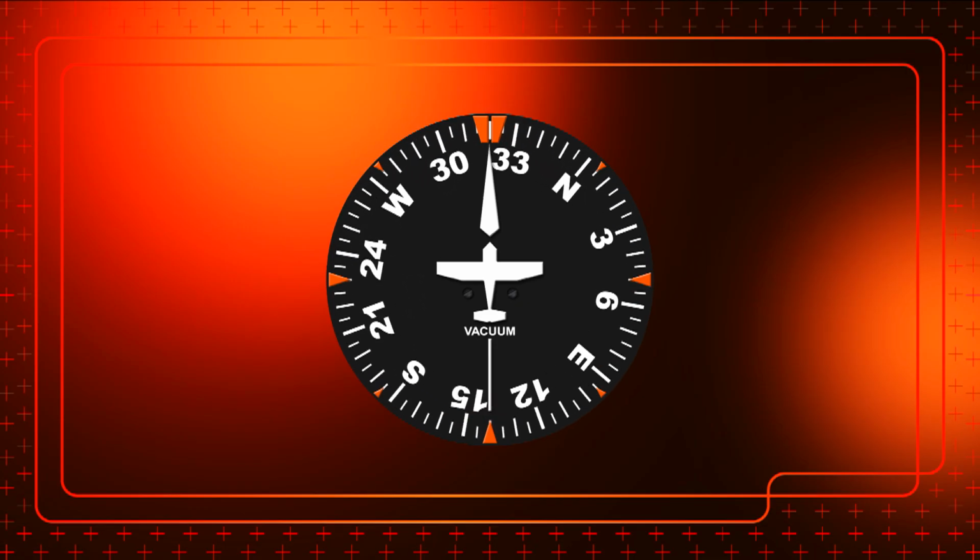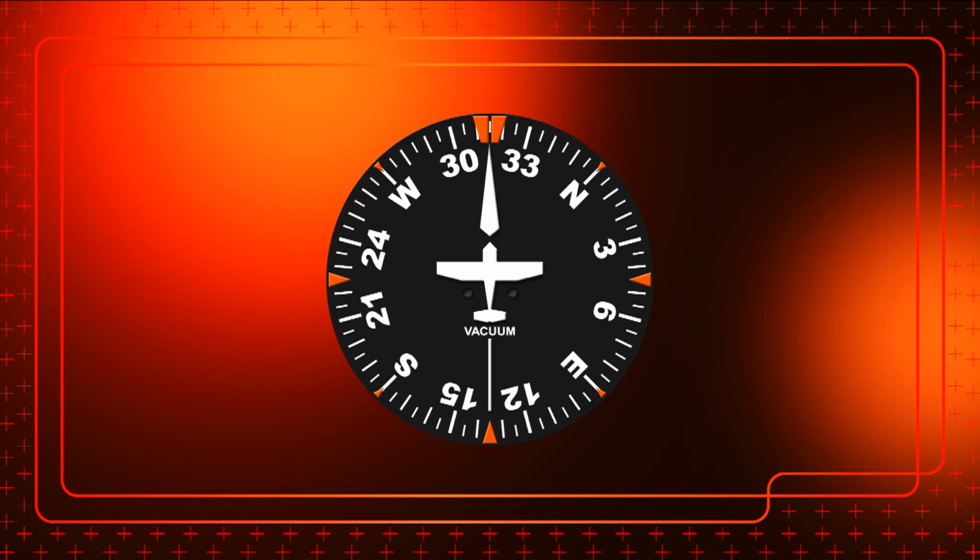This is important, as in some instances, air traffic control will instruct a pilot to turn to an exact angle from their current heading. For example, if you are flying west at 270 degrees and air traffic control instructs you to turn 45 degrees to the right, you can quickly determine what heading you need to turn to by looking at the relative heading marking at 45 degrees to the right, which will tell you that you need to turn to a heading of 315 degrees.